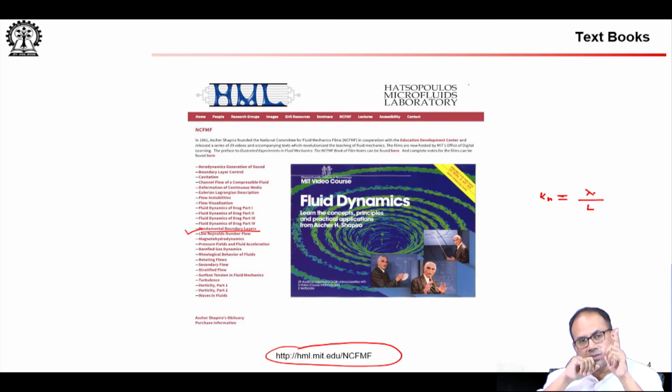In those conditions, depending on the Knudsen number, you can actually start seeing velocity slip and temperature slip. But for most of our applications, that happens at really high altitudes, and those kinds of situations happen in re-entry vehicles. Say the Apollo re-entry, lunar re-entry, or even the space shuttle re-entry. I have to look it up, but it depends on the altitude.